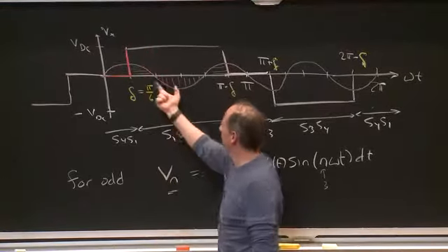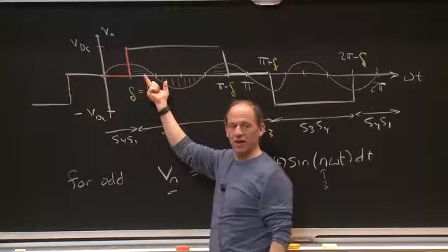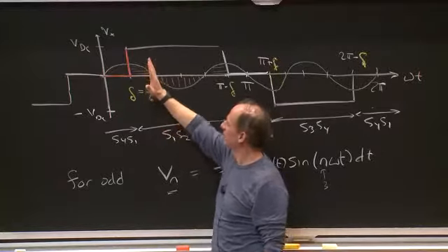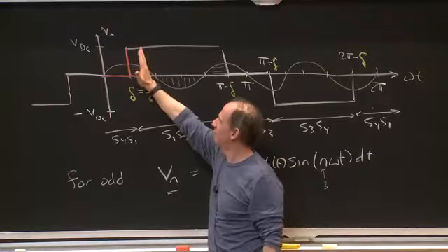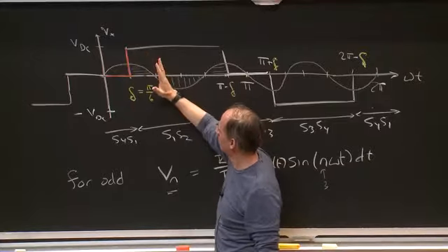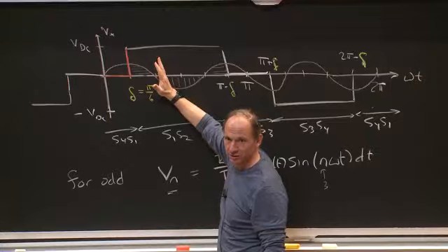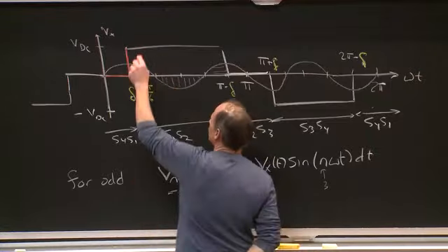And if I cut out a little bit on each side of this, I don't change the fact that the third harmonic's gone, because as long as I make sure the amount of positive area multiplied with the third harmonic balances the amount of negative area with the third harmonic sine wave, I will maintain 0 third harmonic.